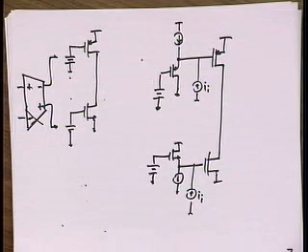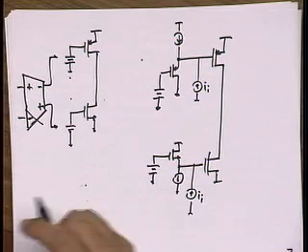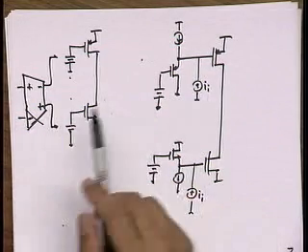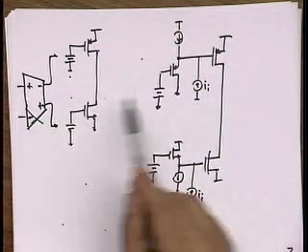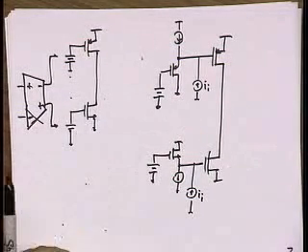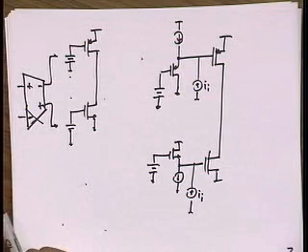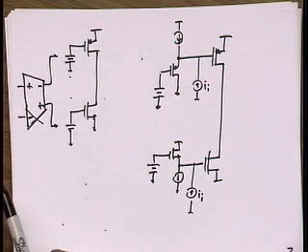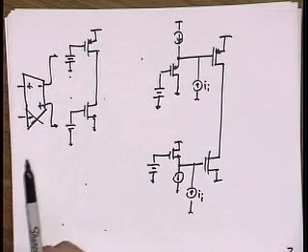Okay, Vincent? No, because you're going to load the OTA. Because the input impedance is pretty small there for the bias circuit. Okay, yeah, that's a reasonable point. I hadn't thought of that, but let's say that's not an issue. Let's say that I'm getting most of my gain from the first stage, and the second stage can have a reasonably small gain. I just need a gain of 5 or 6. Could you do it?